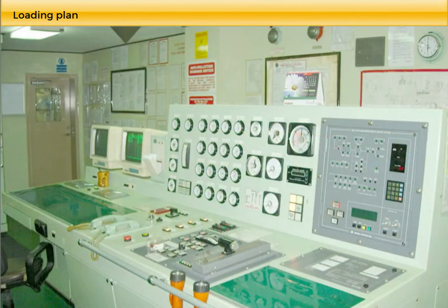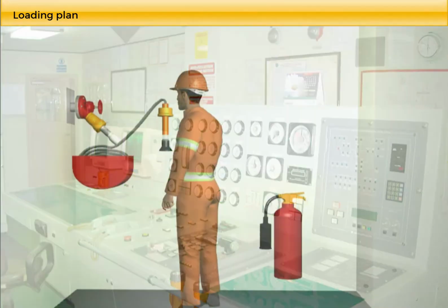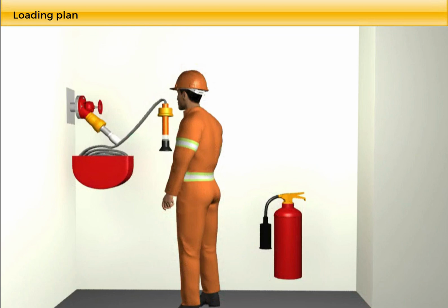In the engine, all the technical systems required by the checklist are to be tested, and the results reported back to the Chief Officer. These tests must include operation of the cargo and inert gas pipelines valve operating systems, hydraulic power packs or boilers for cargo pumps, inert gas systems, ballast and stripping pumps, and alarms and trips of all these.